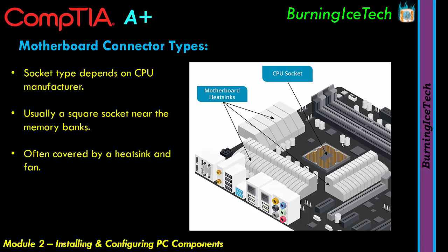Also, you might see that in that little CPU slot, they've got these little plastic ridges. In the picture, they're dead center. In real life, that's not the case. You might find on one side there are 2 little pieces of plastic that go inwards, on the other side it's only 1, and the next side it's 3. And they're normally off center. The CPU is going to have little holes in the sides as well, which align perfectly with those little pieces of plastic sticking out, which also allows you to know how it needs to go in. So that's two ways for you guys to know how to put a CPU in.